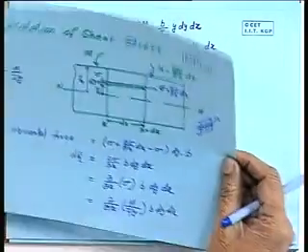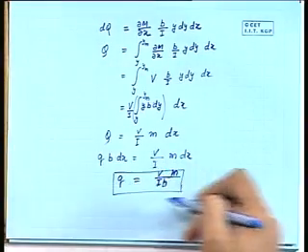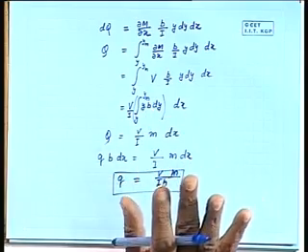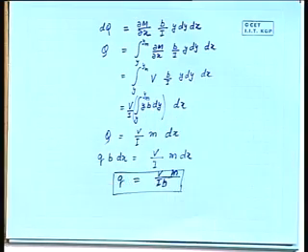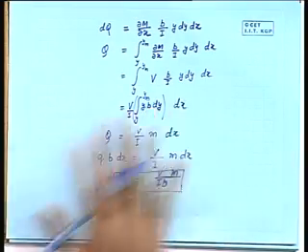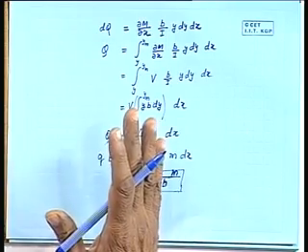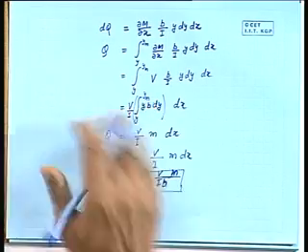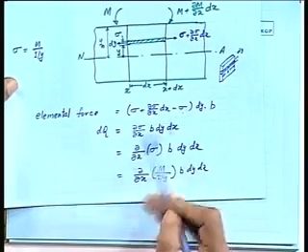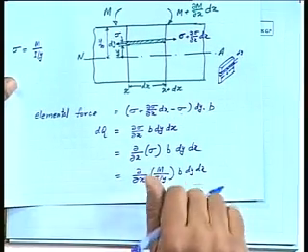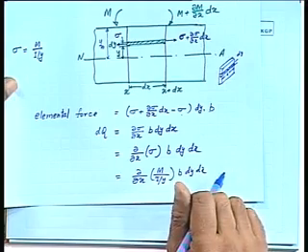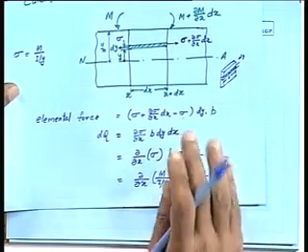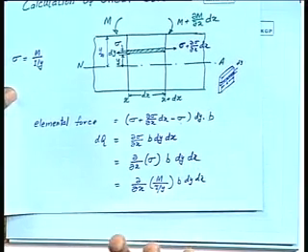now one thing is to be noted here, that this expression which we have derived is an approximate method, because to start with we have assumed that there is no shear stress at the section, because we based our calculation solely on the basis of the bending stress here, and then we have tried to prove that there is a shear stress. Okay. So, therefore, if you go for a very rigorous calculation, then we must go from the theory of elasticity point of view, which we are not doing.